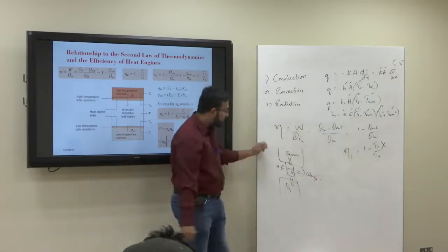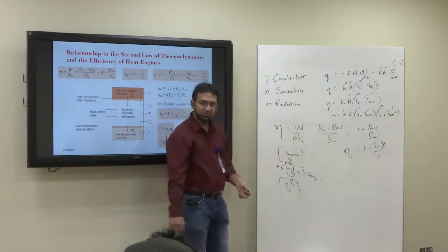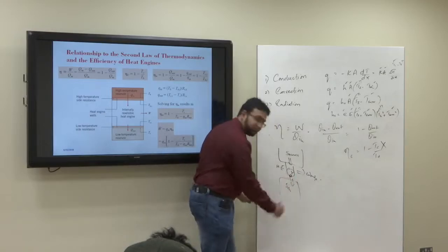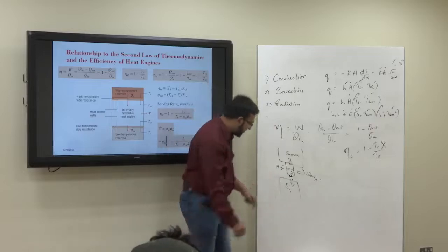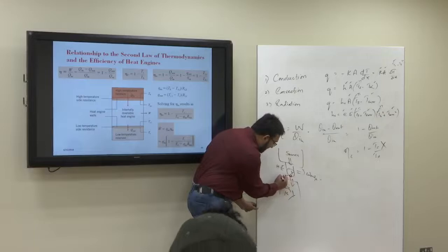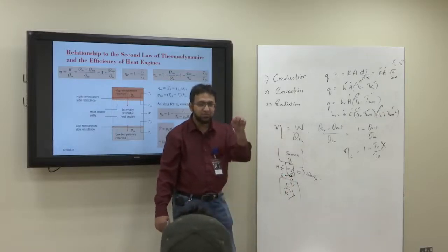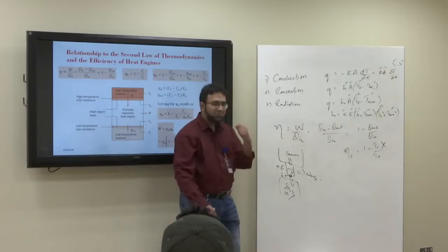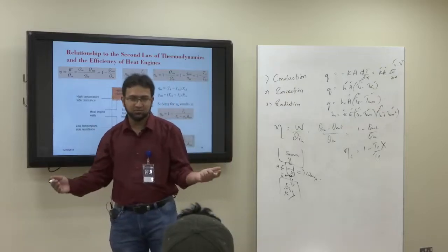Okay, we are using the temperature of the source and the sink. In this case, our sink is this room, let's say 24 degrees centigrade, and here we have the condenser, which is rejecting heat to the sink. So TC, if we consider this as TC, this is wrong. Our TC should be here, right? It should be the condenser temperature.